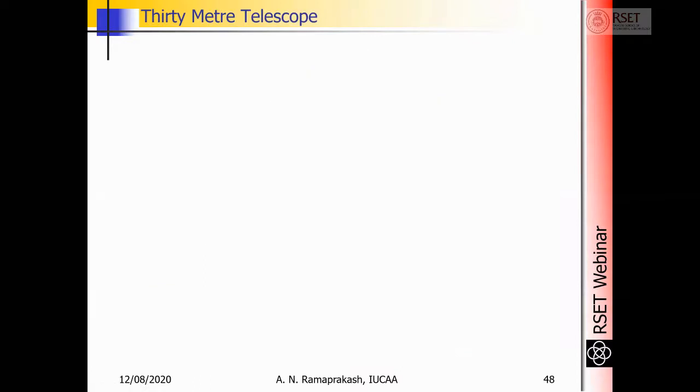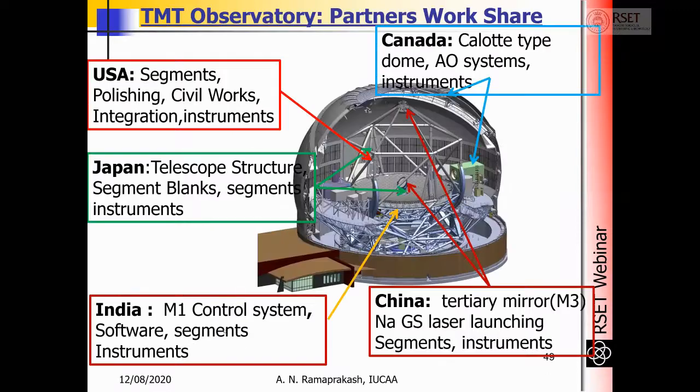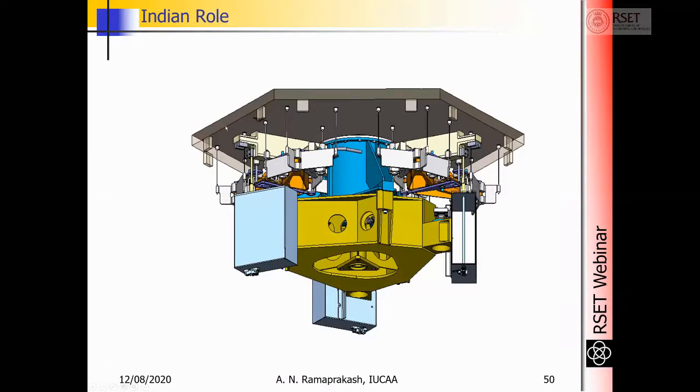And many components of these telescopes are built across the world. And India is making a large number of components of these telescopes. So I will try to highlight what India is making. If you look at this gray thing, it is one of the 500 segments which constitute the primary mirror of the telescope. And for this segment, India is making these sensors which are at the edges of the segments, which make them align with each other to 20 nanometer precision.